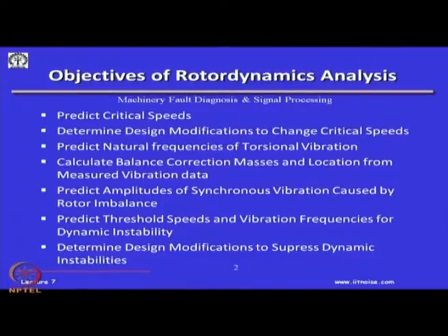The next is, in a rotating system, like the gas turbine we just talked about, if there is a small amount of unbalance in one of the vanes or the blades, once they rotate at high speeds, we will have very high unbalance forces. These forces are radial in nature, and because of these unbalanced forces, we will have forces at the bearing supports, and sometimes these forces could be very high, and we have to ensure how to reduce them, otherwise the bearings are not able to withstand such high forces.